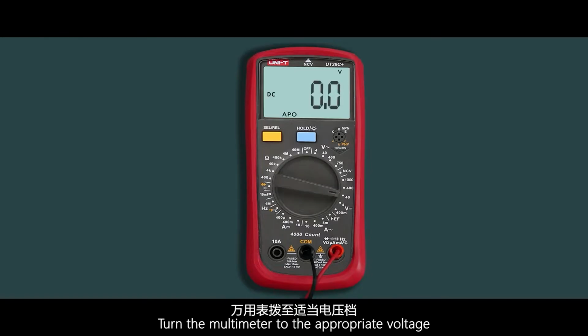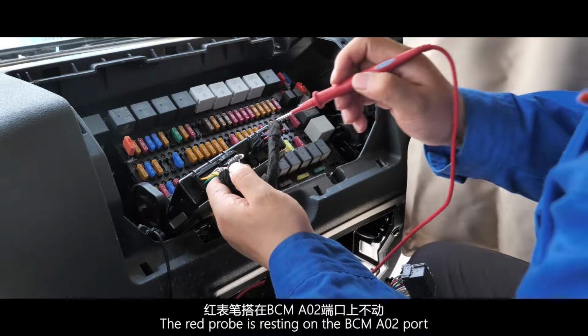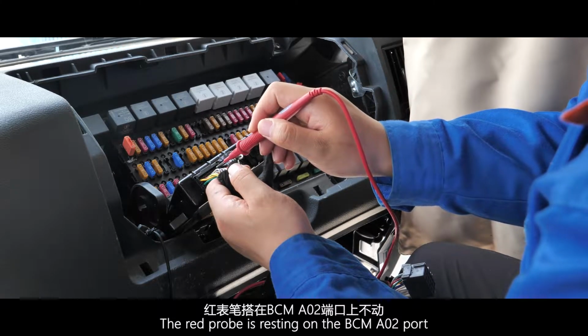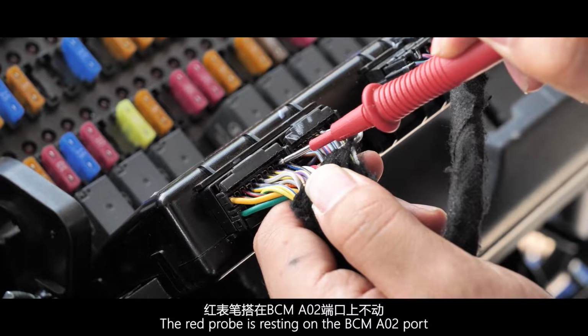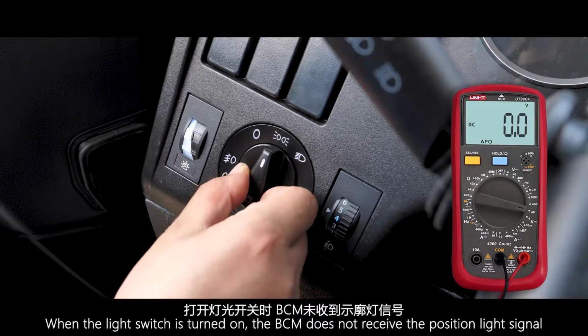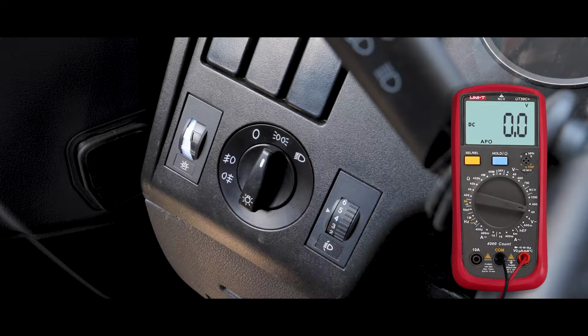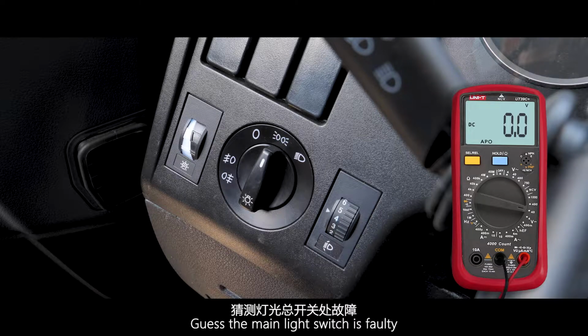Turn the multimeter to the appropriate voltage. Black probe grounding. The red probe is resting on the BCM A02 port. When the light switch is turned on, the BCM does not receive the position light signal. Guess the main light switch is faulty.